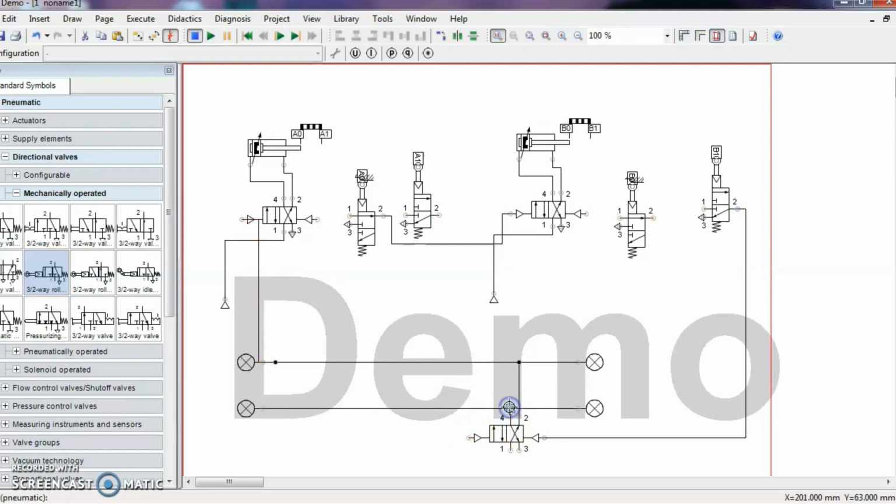So now the flow changes from pipe 1 to pipe 2. Pipe 2 is the last line, you can see there. From the last line we have to join B minus, so in this group the first step is B minus. So we have to join to the right side of the DCV of cylinder B. So now B returns and B is not activated.